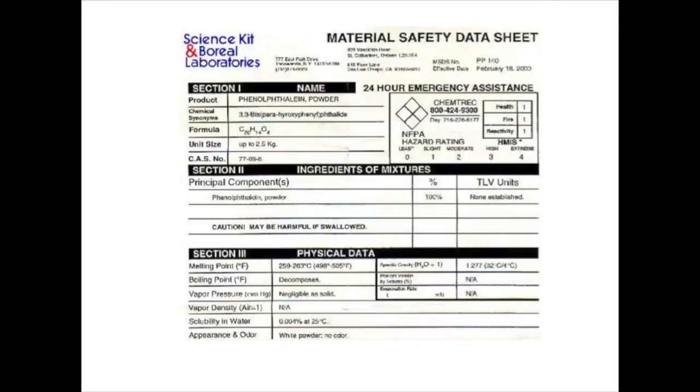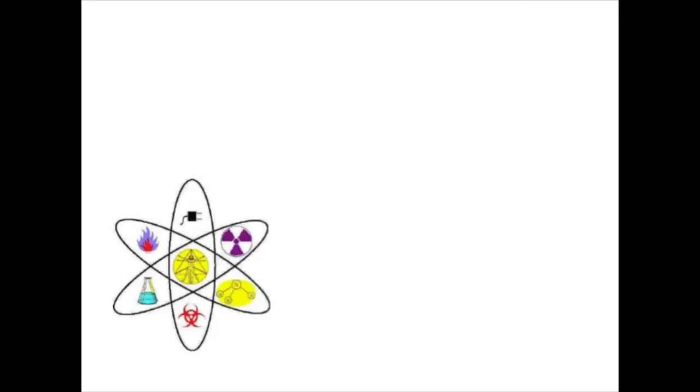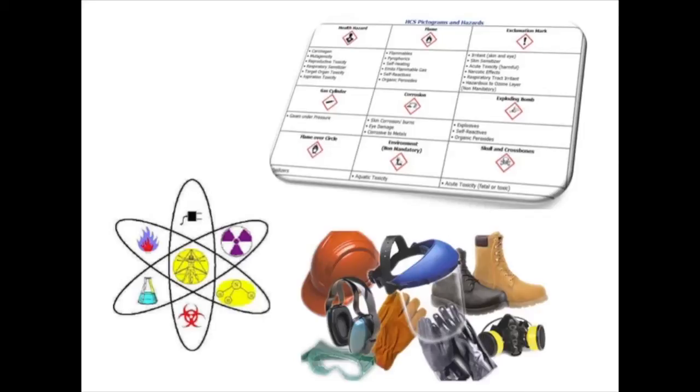As part of that program, the facility maintains a Material Safety Data Sheet or MSDS for each hazardous chemical or material on the site. The MSDS outlines chemical and physical characteristics, exposure hazards, and exposure controls, including PPE. Workers have access to MSDSs while at the plant and may locate a specific MSDS by using the Hazardous Chemical Inventory. The inventory is a list of all chemicals at the site and is located with the MSDS book in each department or in the Safety Center.